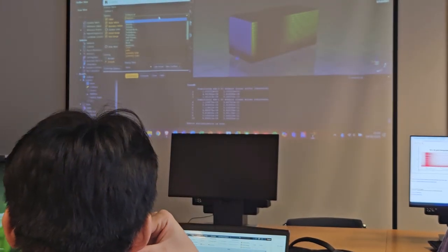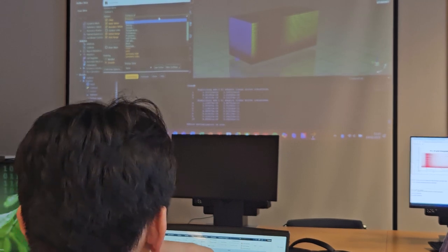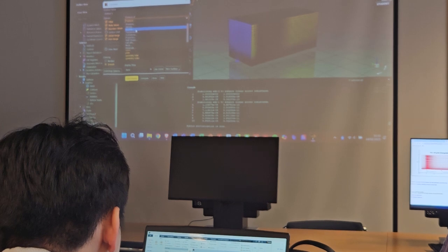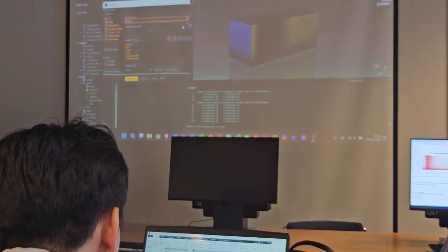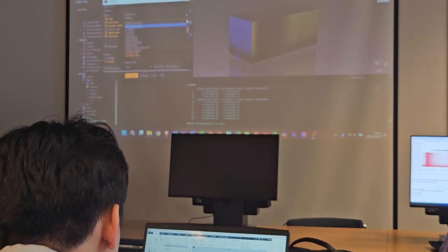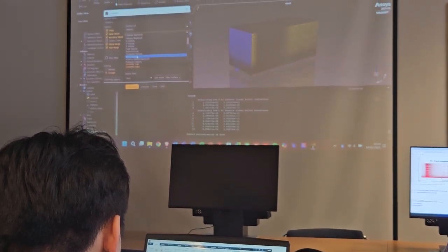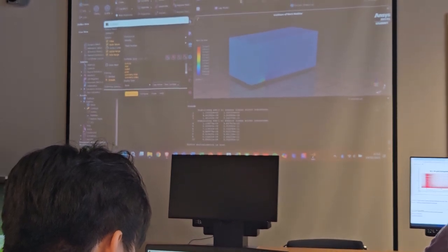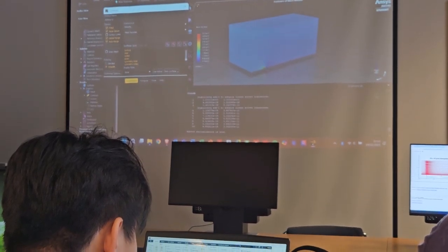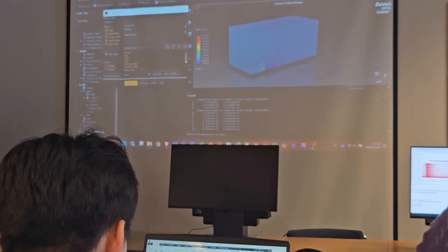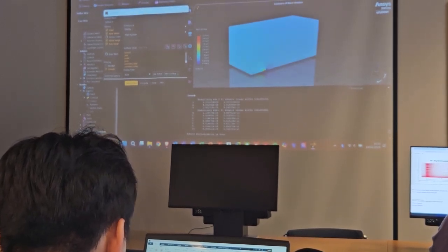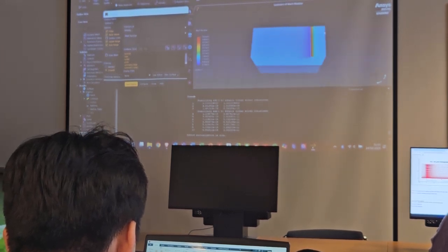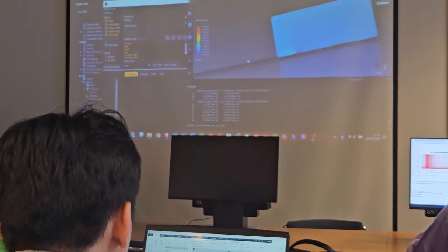But right now we can plot the Mach number for the hybrid initialization. So you can select contours of velocity, and then in the second row here, instead of velocity magnitude, you can plot the Mach number. There is that option. And save display. The colors are not really nice. Typically I change them in view. There is this option lighting. I deselect that option. So now that looks better. Okay, so this is the initialization of the case.